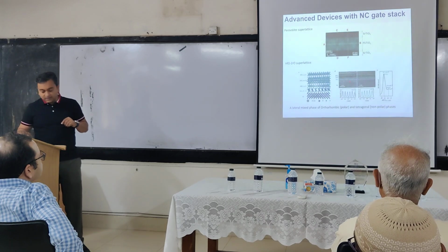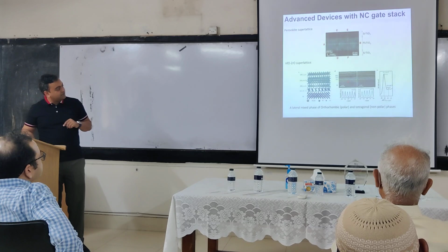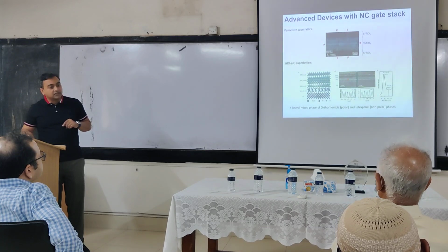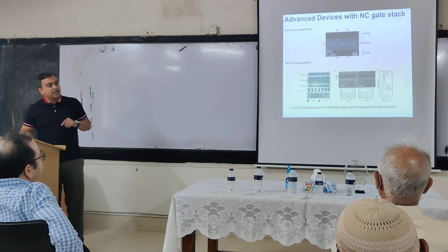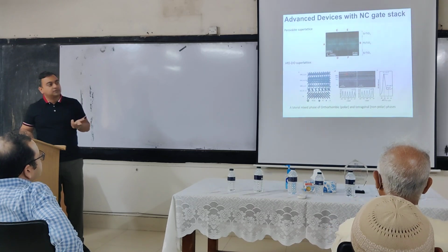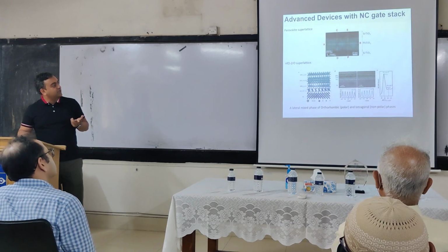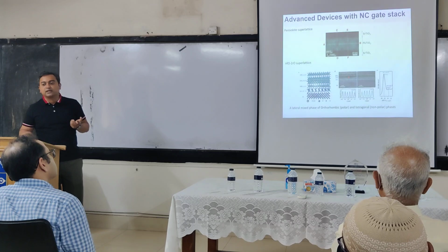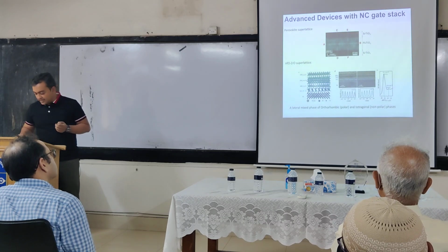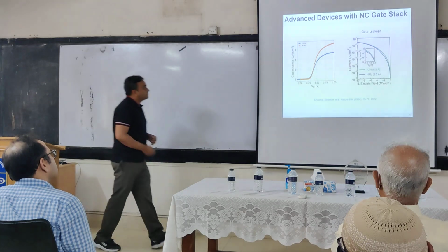So what I'm showing here is exactly what will be used in today's MOSFETs, where I have silicon, a little bit of silicon dioxide, and then 18 angstrom, 1.8 nanometer of high K dielectric, which in our case we are making a superlattice with our ferroelectric, exactly that 1.8 nanometer. Okay? And we immediately see the performance boost.